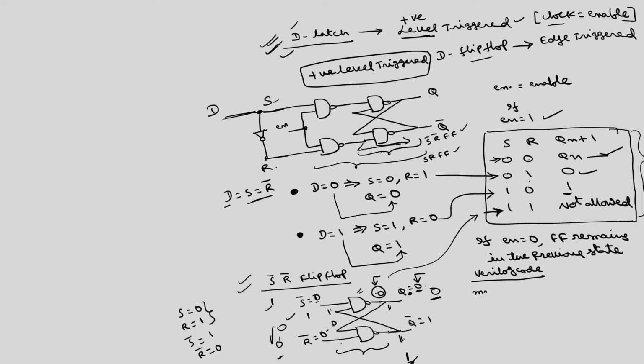I will give the module name, I will write all lowercase letters, S B R B F F flip flop. This was the notation I am using. S B stands for the S bar input, R B stands for R bar, and FF for flip flop.